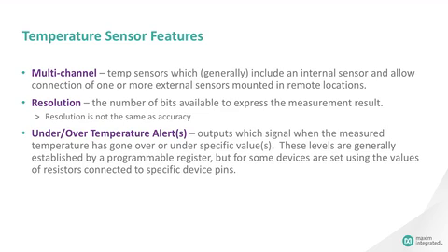Many thermal measurement devices include features above and beyond the basic temperature measurement functionality. While the most common ones are shown here, you'll encounter a number of interesting and unique features beyond those as you begin looking at specific devices. A remote temperature sensor may have one or more channels of remote sensing. Multi-channel remote temperature sensors may be useful in cases where there are multiple sensing transistors on a single board.